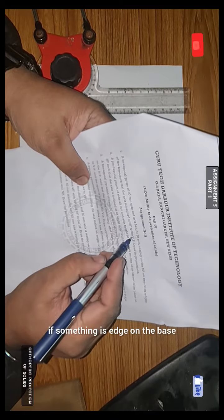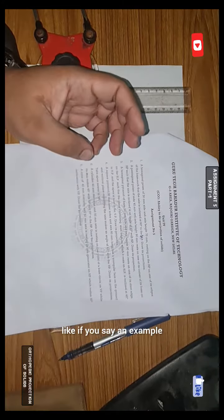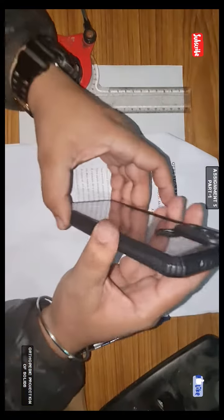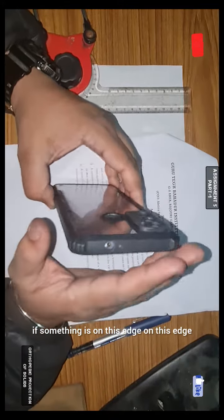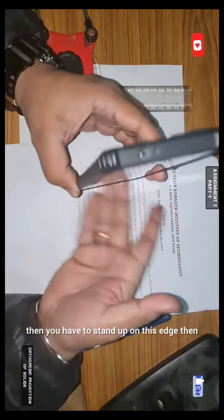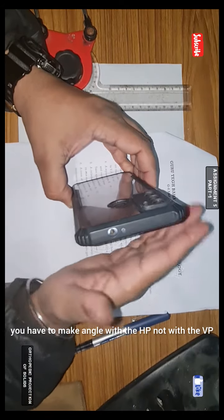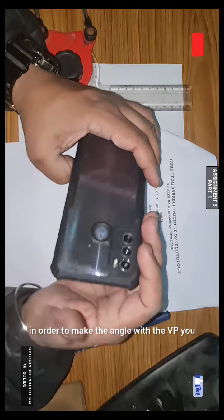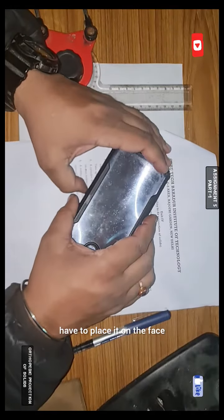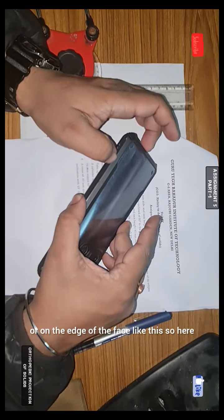If something is on the edge of the base, like if you say an example, if something is on this edge, then you have to stand it up on this edge, then you have to make the angle with the HP, not with the VP. In order to make the angle with the VP, you have to place it on the face or on the edge of the face, like this.